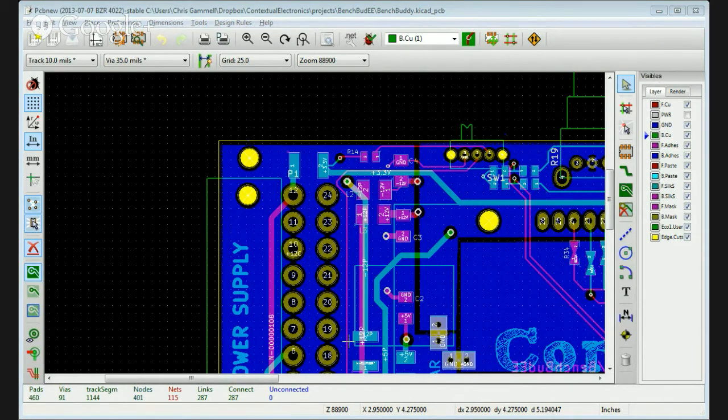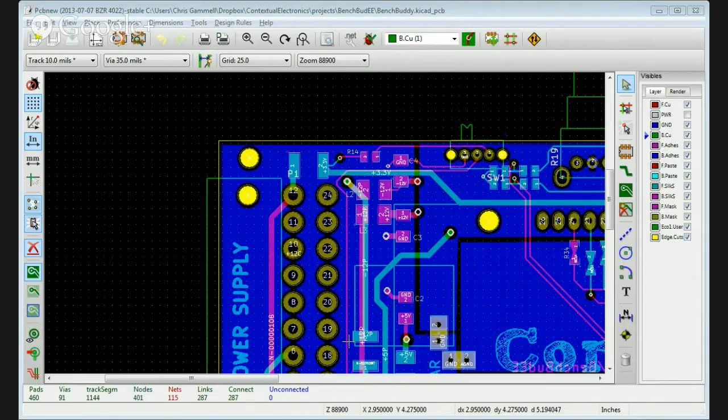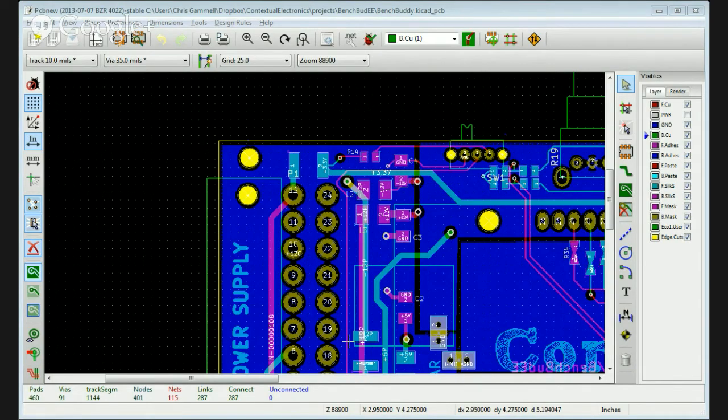So James had asked Wes, what did you use for the supply rails on the MCP 3901, the L5 inductor? I don't know what that means. I put a 0 ohm resistor there. I guess that's to tie the analog VDD and digital VDD together. So I just used a 0 ohm. Okay, so you didn't use the ferrite bead? I wasn't sure what you had in mind to put there, so no, I didn't.